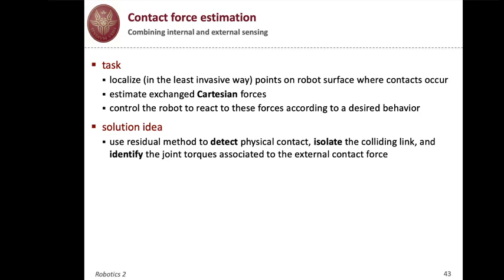use the residual method to detect that the physical contact occurred. With monitoring the generalized momentum, we can also isolate which was the colliding link, and we have a filtered version of the joint torque associated to the external contact force. So far is what we have learned.